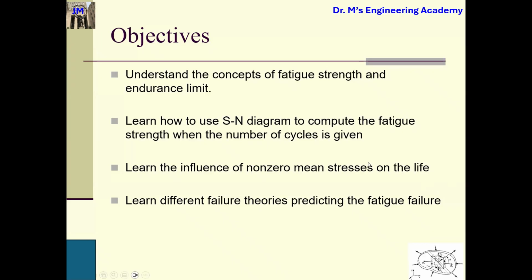Questions regarding this one? What I might ask you guys, use your own words, tell me why fatigue is important and why fatigue is more dangerous than static loading. Right? So the key point is that the number of cycles plays an important role. Even though the stress level you apply is much, much lower than the yield strength, as time goes, as the number of cycles increases, it will break.